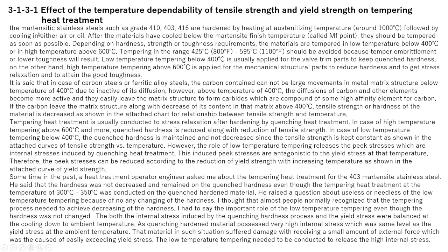The martensitic stainless steels such as grades 410, 403, and 416 are hardened by heating at an austenitizing temperature of around 1000 degrees Celsius, 1800 to 1900 Fahrenheit, followed by cooling in air or oil.